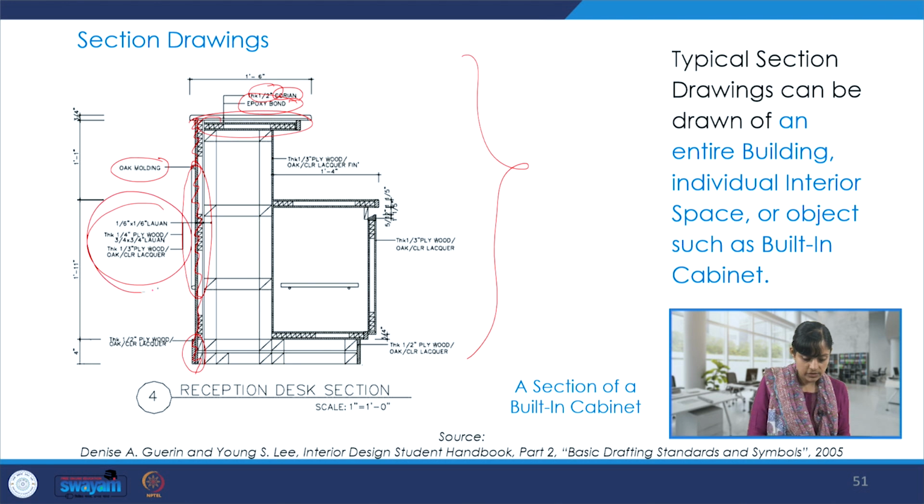Also these kinds of details again, which plywood, what make, what kind of inches, because there are also standard sizes available in the market. There could be customized details also, but there are standard sizes available, and then we try to put those dimensions in drawings over here if we are procuring those standard typologies. Whether there is a lacquer finish or it's a varnish done over there. So all these details a section helps us understand.